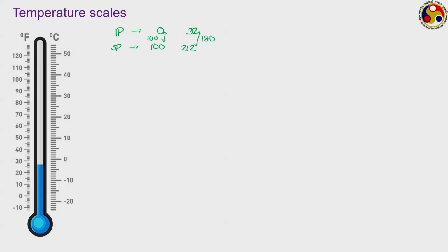So, what we do in either scale, we specify the ice point and the steam point with the corresponding values, and then the distance between these two, that is 100 units in case of Celsius scale and 180 units in case of Fahrenheit scale, they are given equal divisions. We hardly go for calibration at some intermediate temperatures, like we hardly take any reading at 20 degree Celsius, 40 degree Celsius or maybe 100 degree Fahrenheit. We rather just make equal divisions,